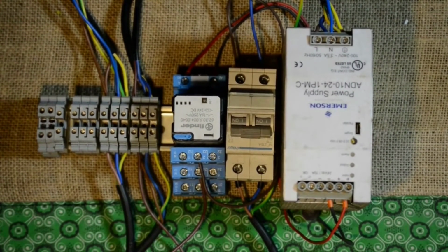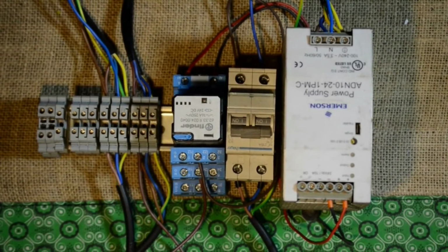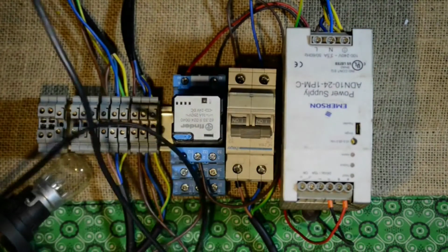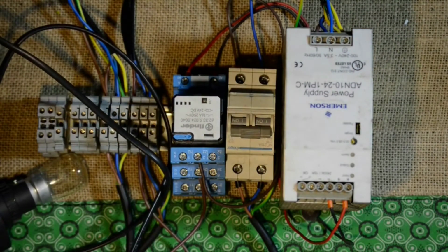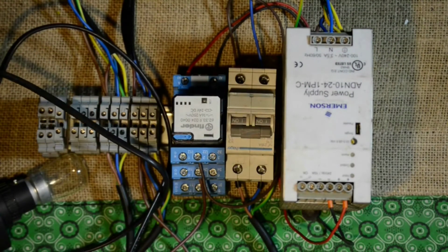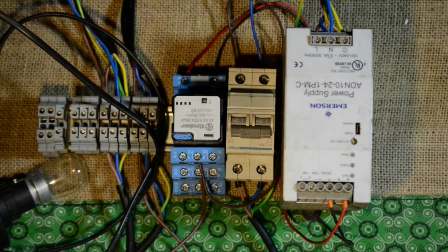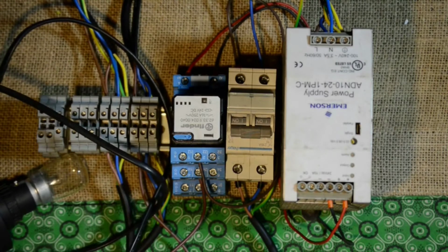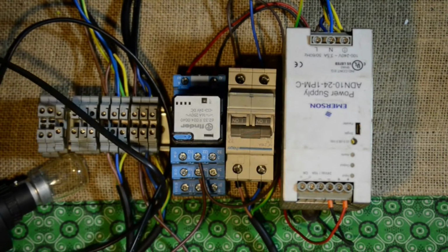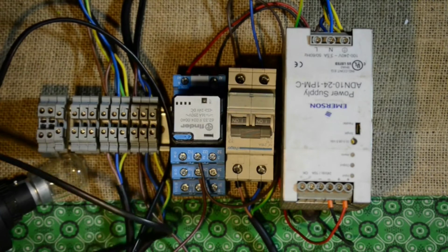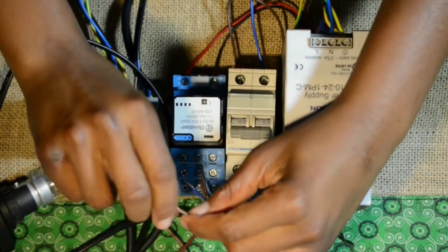So our load in this case is a smaller wattage bulb, right? It's an incandescent bulb. This is something that I use always when I'm working with these circuits or any other circuit where I need to test the load. Start with a smaller load. That way, if something is wrong, you might damage this smaller load. It's nothing expensive, you know.